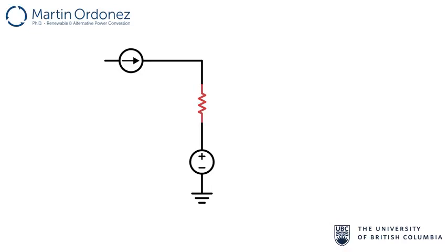Let's first consider no heatsink. In this case, the problem has only one thermal resistance. According to the datasheet, the conduction resistance between MOSFET and ambient is 62.5 degrees Celsius per watt.